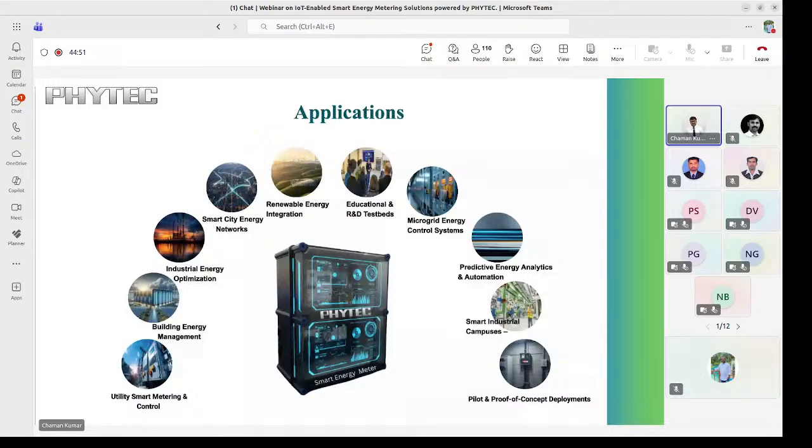And this is the basic architecture of this PLC system, where we have a PLC modem, we have a load, and this PLC modem is wired through the power line, and this is also going to the main PLC, that is the RB-DCU. So they form one power network. Then once the data reaches the DCU, it will be sent to the HES and then to the dashboard.